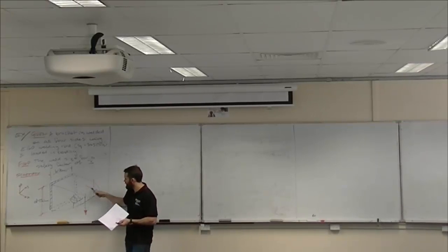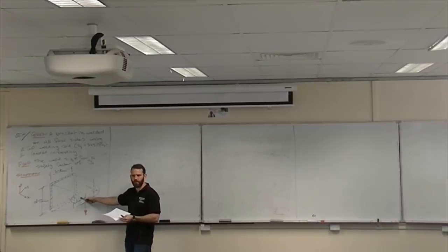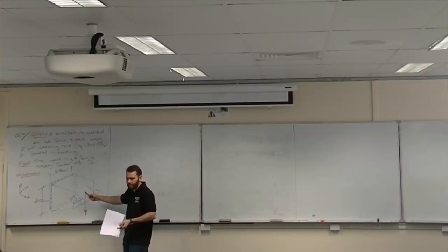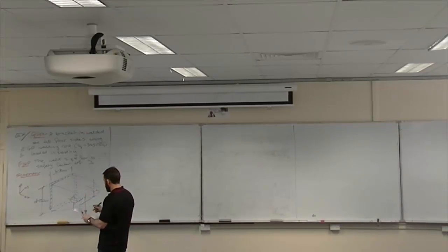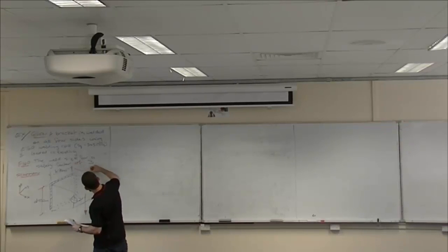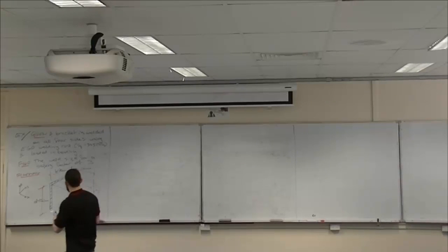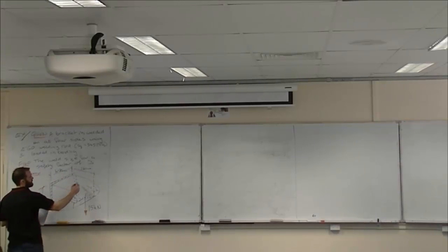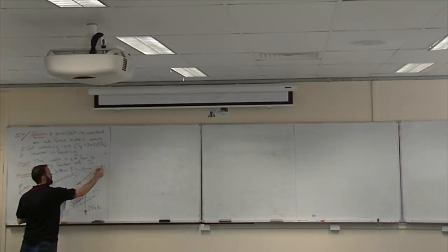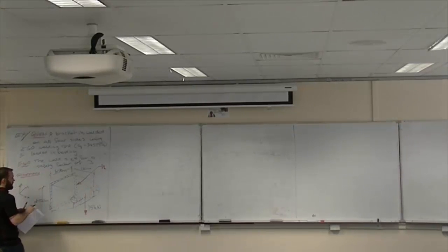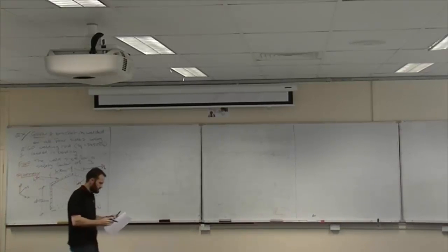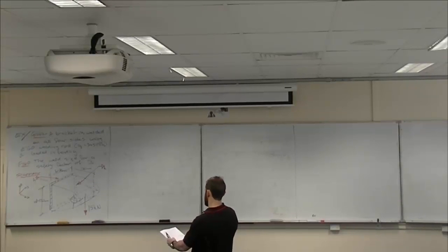The force is applied, that's a hole, so that would be a pin, and maybe you have a clevis on the side of it or whatever, but the effective force will be applied at the centre of that pin. It might be distributed across, but as far as the bending is concerned, it's all the same. The last thing we need to do is indicate how far out that is. That cantilever is 160 millimetres. Then we draw the weld on the sides, top, bottom, left and right, with 2 arrows. I've got everything. Good enough.